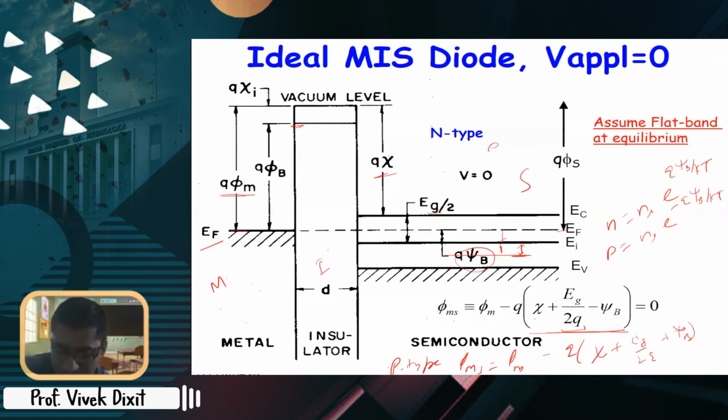So these electrons in the bulk should come to the surface. Now they will come to the surface when you apply a positive voltage here. Now by applying the positive voltage, what will happen to the Fermi level? It will go up or go down? Now voltage is positive, that is energy is minus QV, negative, right? So this Fermi level will actually go down. So basically you will have some kind of this thing here and this thing here, right?